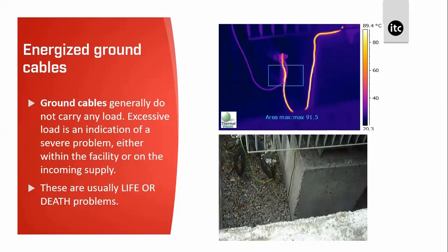And as the earthing system is not normally designed to take continuous load, the components are likely to fail if exposed to excessive load. And once a component fails, the fault path is now gone, and typically you are left with some live equipment looking for a new path. And this can be live metalwork, either on electrical equipment itself or, in extreme cases, other metal like pipework or building structure. And this can stay like this for quite some time, waiting for a new path. Eventually, however, it will find a path through a person, animal, or object that happens to come in contact with the live metal.